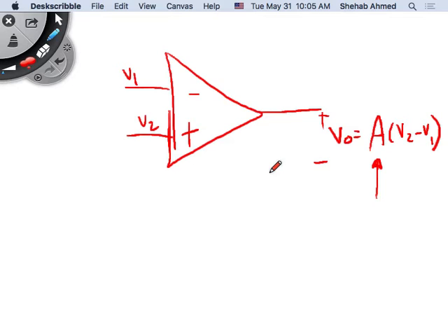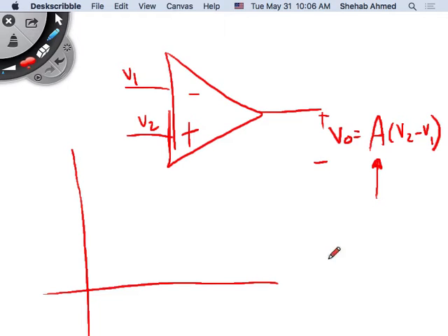And then with the assumptions that we talked about today, we said that it is not really infinity, it's limited. But from a manufacturing perspective, it's very difficult to define it as a value. So what is the best way to estimate it from a design perspective? The best way is by looking at Ft. You take your point from Ft from the datasheet. It was 1.5 megahertz for the 741 op-amp. And then you go to your magnitude of A plot.